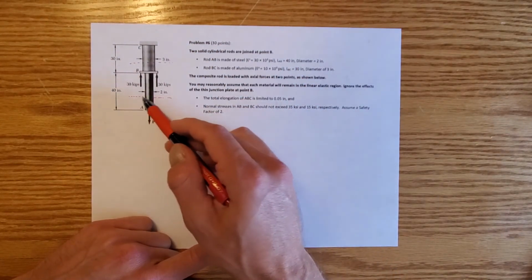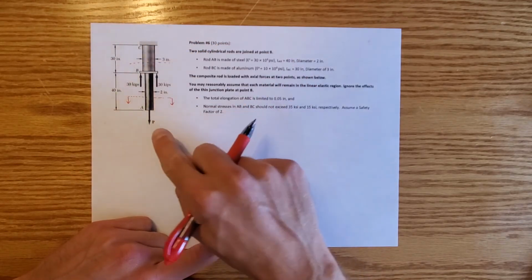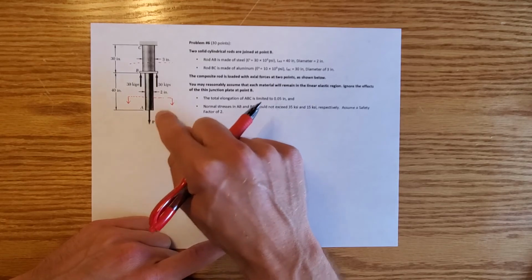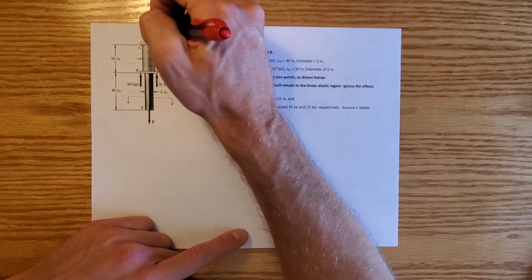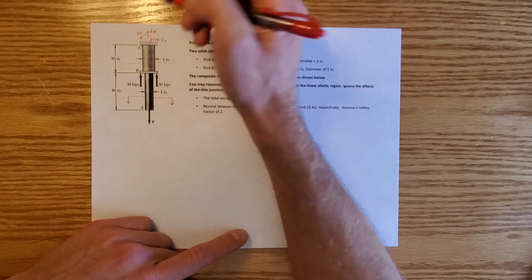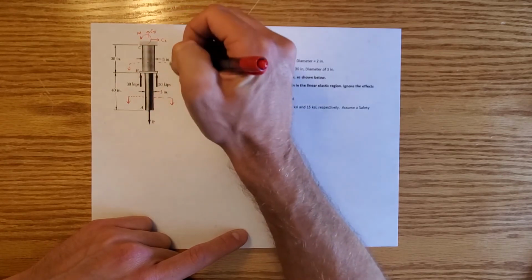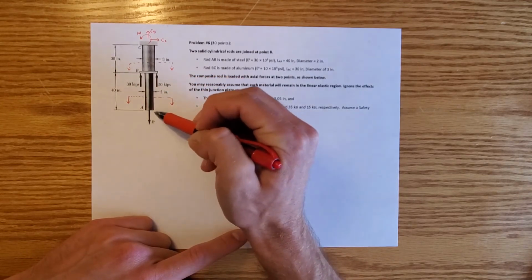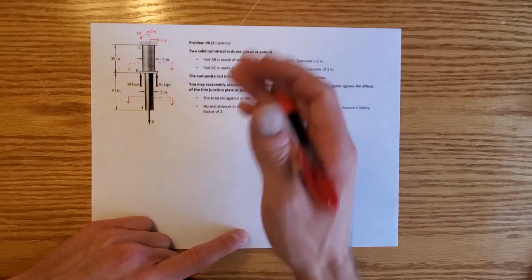You can see that for the cut we make through rod AB, we're going to want to look down because we want to be as lazy as possible and choose the side with the least unknowns. That would be looking down because the only thing we would see would be P. If we looked up, we would have seen this 30 kips, and 3 reaction forces up here, which would have been CY, CX, and a moment. So we don't want to look that way, and that also holds true for rod BC. We're going to cut through the rod and look down, so that all we see is these 30 kip forces here and this P. Now that we've made both of these cuts, I'm going to draw the free body diagrams of both of those systems, and then we'll get started with the rest.